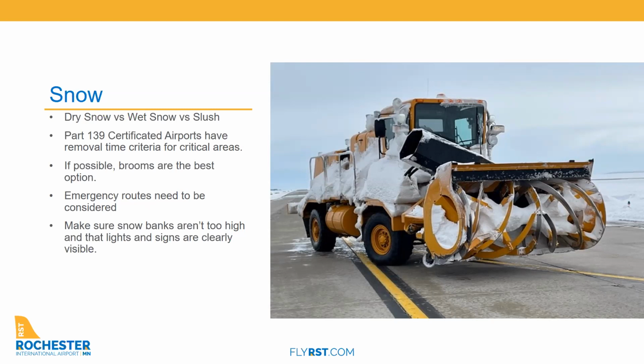Certainly at our Part 139 certificated airports, we have a snow removal time criteria for our critical areas through our snow and ice control plan. I understand many of the airports listening today probably can't justify brooms, but I will tell you brooms are absolutely the best piece of equipment for taking off snow. We broom probably 90% of the snowfalls, and we only supplement the brooms with plows to remove the heavier snow. And certainly, the larger airports are moving to multi-function equipment, where there's a plow on the front and a tow-behind broom, so they're able to do both functions at the same time.